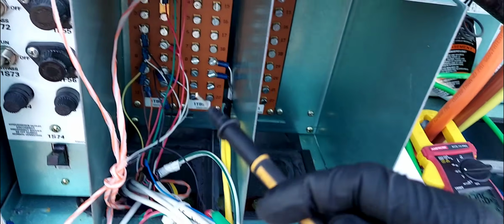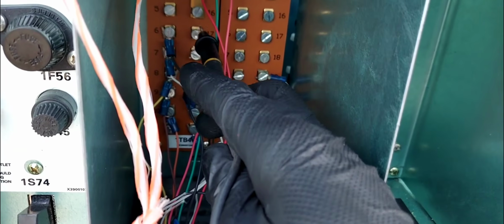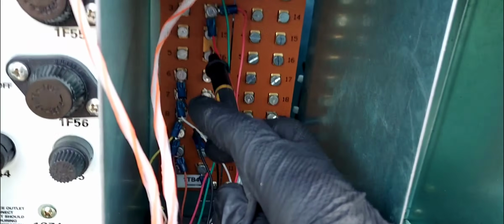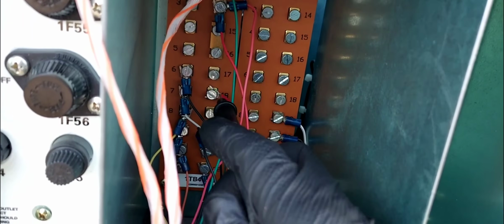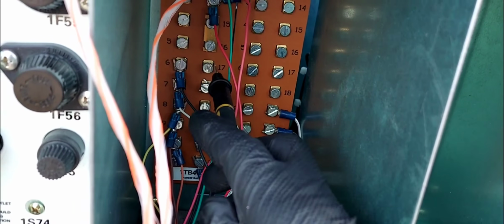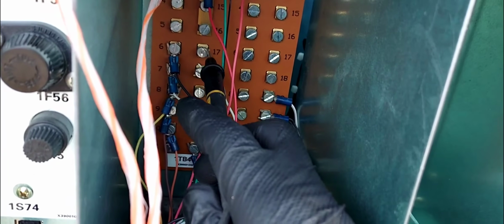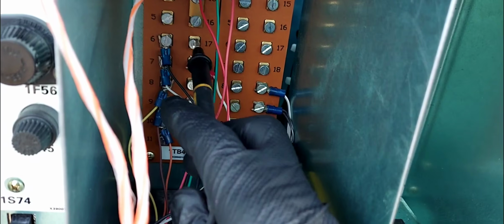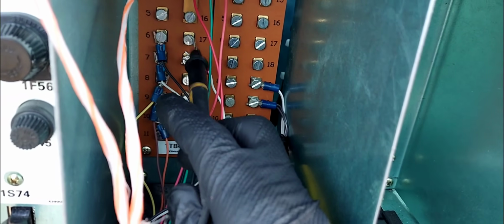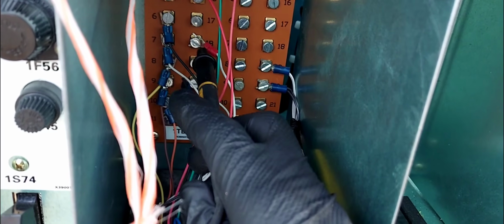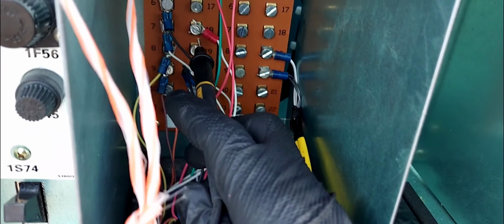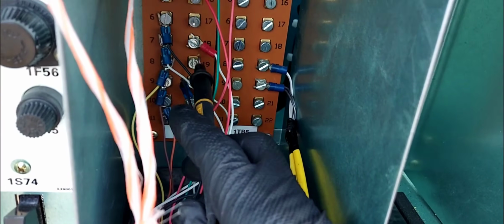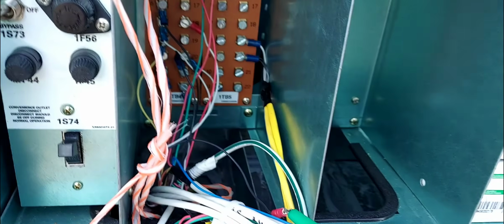If out of the box, usually these points right here came with a jumper like this one. See this one right here? A copper jumper. Out of the box from the factory, there was one like this across 17 and 18. Now once you remove it, like I said, it will go into external stop, but you can put whatever switch you want to control that. So in this case, there was in fact a switch hooked up to it, but that switch is closed. That is not the issue.